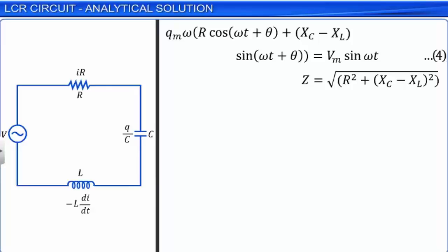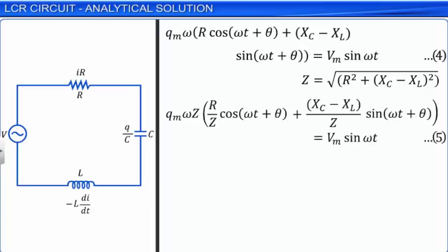If sin φ is the difference of capacitive and inductive reactance divided by the circuit impedance, that is, sin φ is equal to (Xc minus Xl) by Z, where φ is the phase difference between the instantaneous current and the voltage, then cos φ gives the relation between the resistance and the circuit impedance, that is, cos φ is equal to R by Z.